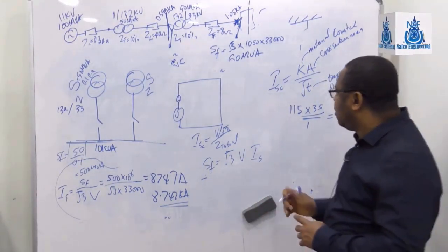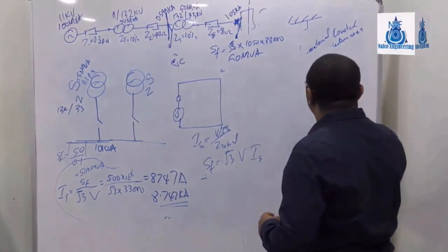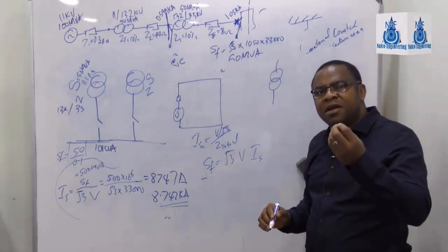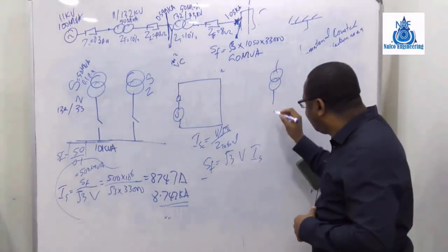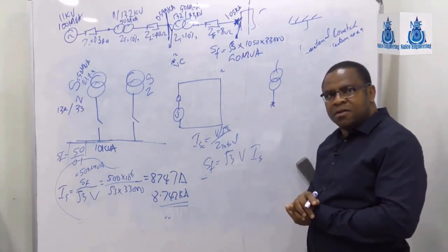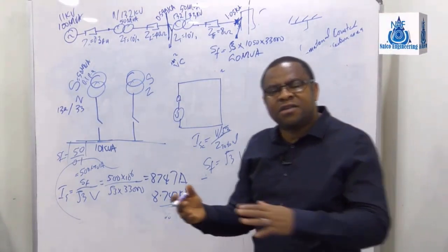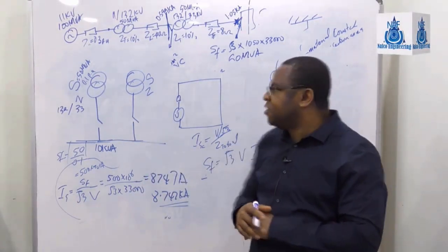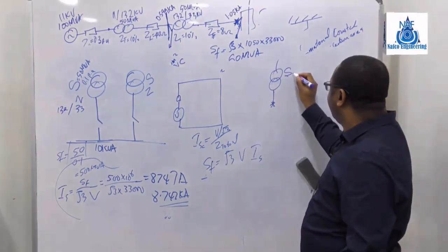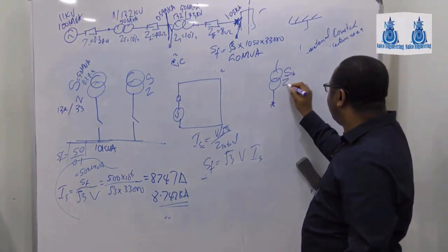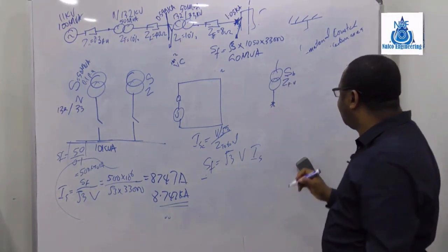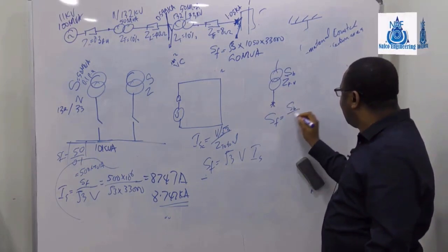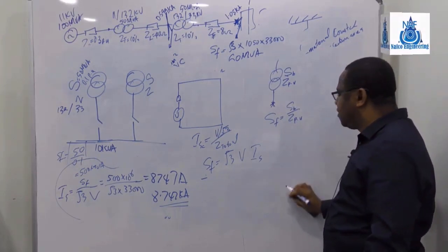Right? So if I have a transformer, let's say I got a transformer like that, and I know the fault level at this point, do you know that you can still calculate, even with the fault level, go back to the transformer impedance in ohms? Because if I have this as S base, and I have this as Z in per unit for the transformer, and we say that S fault is the same thing as S base over Z in per unit, right?